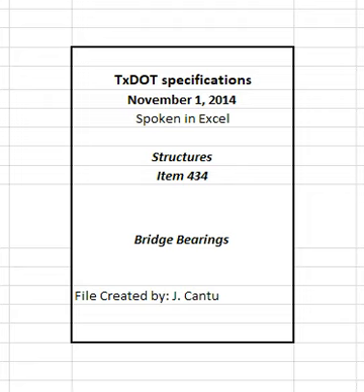2.2.1.2 Laminated elastomeric bearing pad and steel plate. Furnish laminated elastomeric bearing pads in accordance with sections 434.2.1, plain and laminated elastomeric bearings, and 434.3.1, plain and laminated elastomeric bearings. Provide steel plates attached to laminated elastomeric bearing pads in accordance with the plans. Table 1. Required PTFE physical properties. See table in specifications.